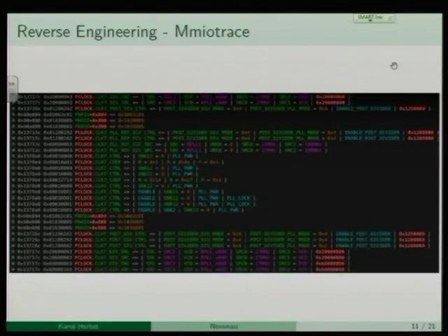So on the left side, there's a flag for read and write, some address, some value, and then we have a database with documentation. If we have an entry for this address, we can print what was written or read there. This example is from a clocking sequence where the Nvidia driver is clocking an engine on the GPU, and we can read out what value got written into what hardware register.